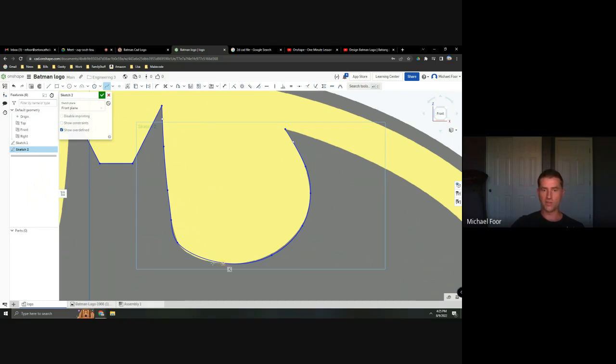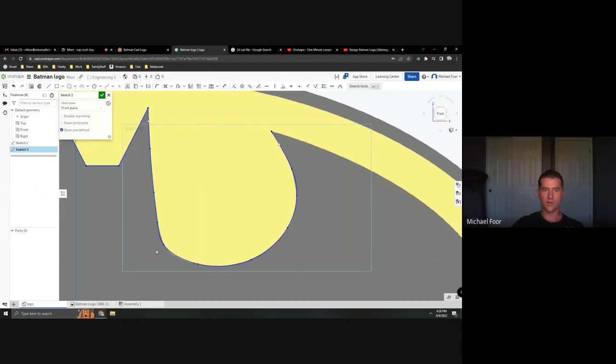Now I don't want to just start clicking on points and moving them, because if you notice right here, my spline tool is still selected. So if I click somewhere, it's going to make another spline, which, let me explain, it's bad. Dead joke. So we'll hit escape, and we notice that the spline is no longer selected. And now I can actually go back and tweak these points. So I can just click on them, move them around, and get them situated the way that I want them.